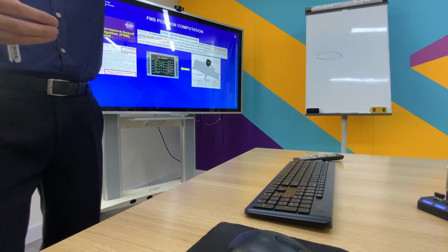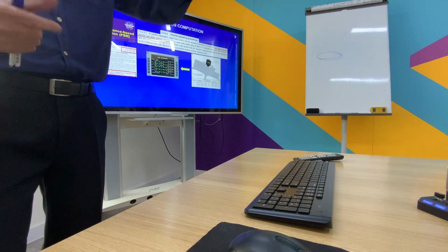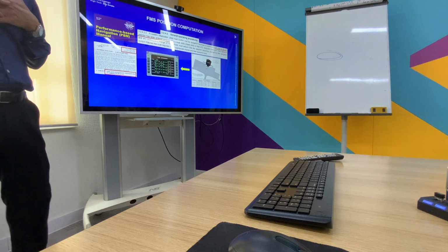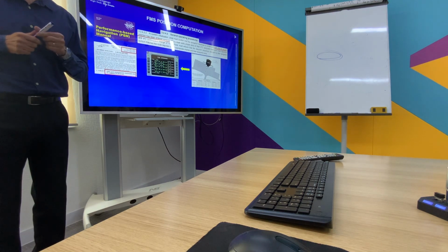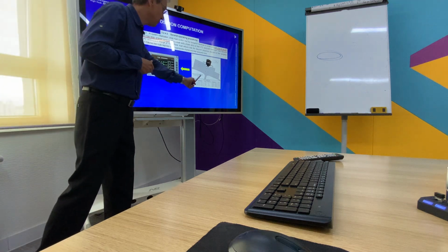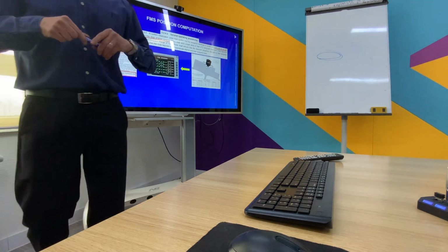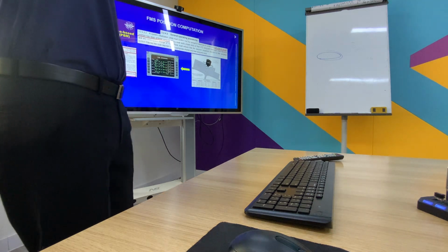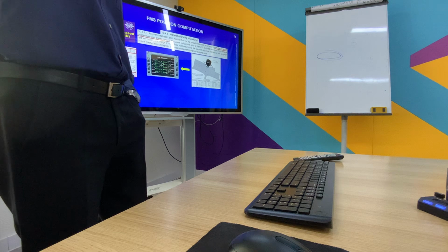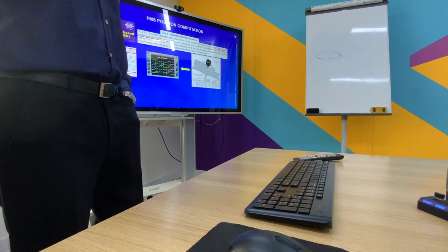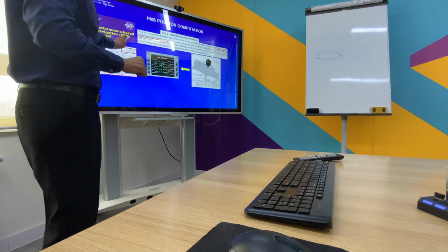That's why we see the airplane's departure airport already selected on the FMS. But it's up to us pilots to check if this position is correct. That's why we have the coordinates for every gate on the airport charts, and that's why we have a plate in front of us, maybe in yellow, with the coordinates. What I suggest is not written in the Embraer SOP, but it's in the regulation.